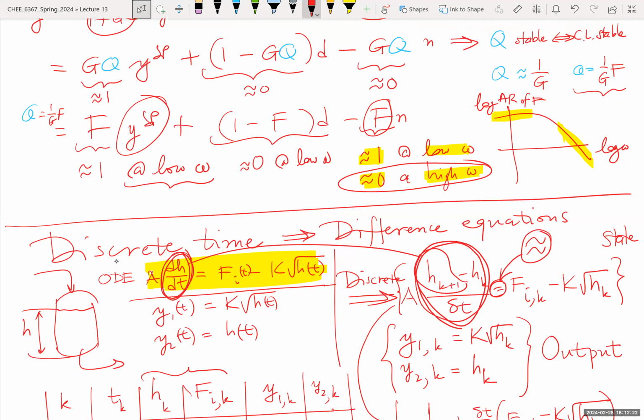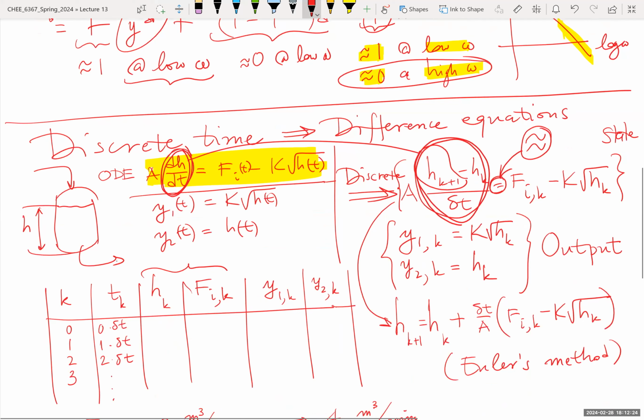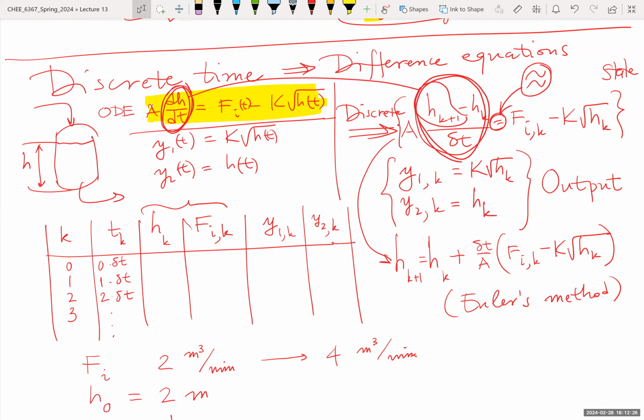It turns out that if my system is linear, there is actually a very good way, an easy way actually, to create a discrete time system which matches the continuous time system exactly. If I have continuous lines and I sample these lines, my model predicts the points exactly, not approximately. And this is useful for controller design.